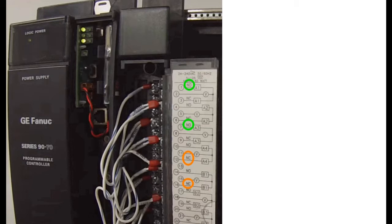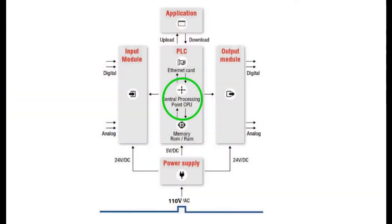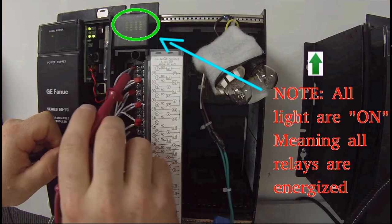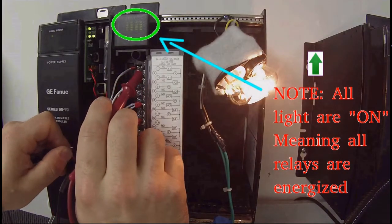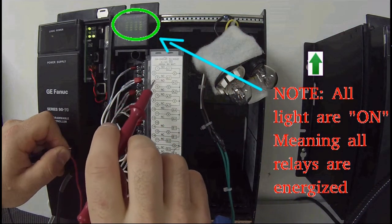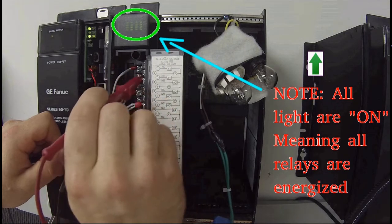Now I will show a short video that I found online. Notice that this technician will test terminal 1 normally open and terminal 3 normally closed. Terminal 2 is the one that provides power to the relay, so it won't get tested. This is the signal that is controlled by the CPU. Normally open number 1 should be on. Okay. And then terminal number 3, normally closed, should be off because the switch has changed.